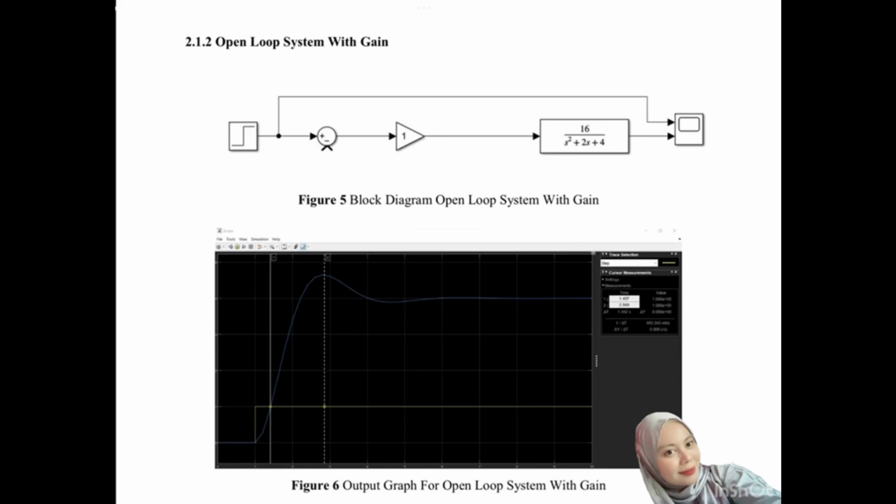Lastly, every control system designer aims for a stable system, since stability is an important factor for a system to behave as expected. For high efficiency and cost effectiveness in some scenarios, we need to push the system operation up to saturation regions or non-linearities. In such systems, relative stability is a significant parameter. Relative stability is the measure of how close the system is to instability. It is usually defined using gain margin and phase margin. If you know the transfer function having a gain in the system, calculating the gain margin is an easy way to check for relative stability.